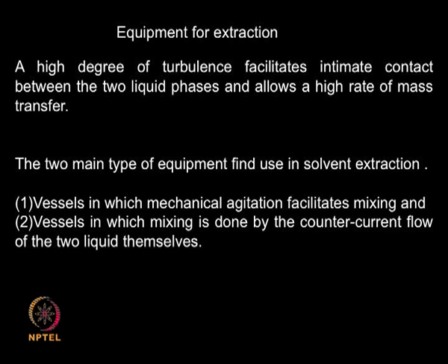There are many equipments used for extraction. In your lab, no problem, you will have something called a separating funnel. You take your broth, you add some solvent, mix them, and then leave it for separating. So a separating funnel will be slowly tapering down with a bottom discharge. So after mixing them thoroughly, you will allow them to separate out into two layers, and then the bottom layer you remove it by opening a cork which is located at the bottom of your separating funnel.